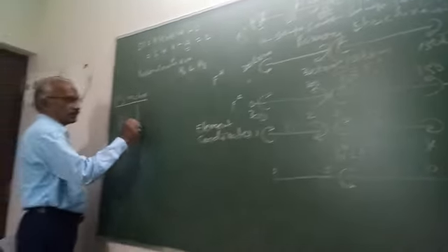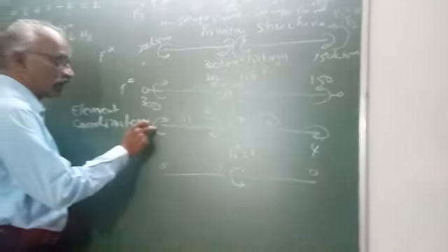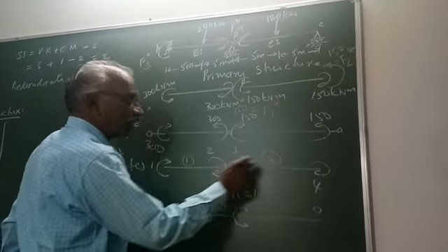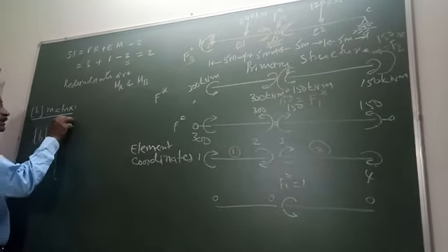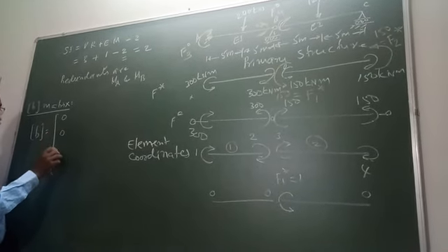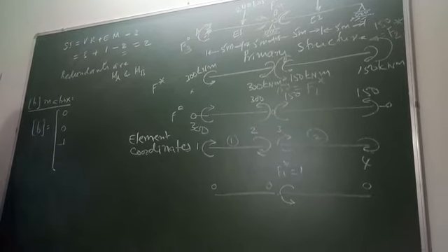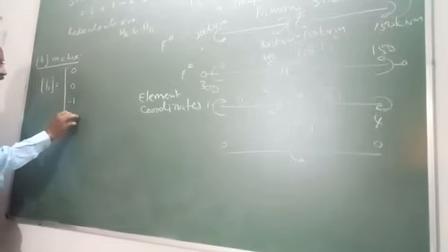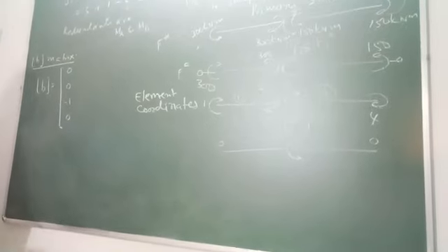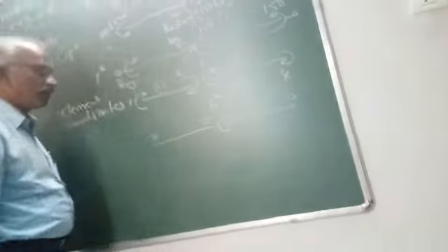So, first column, we have to write in the same order along the element coordinates 1, 2, 3 and 4. At 1 it is 0, at 2 it is 0, at 3 it is minus 1 because it is anti-clockwise. We take the value in the same direction, and 4 is 0. Of course, in some of the books this will be applied in the clockwise direction.